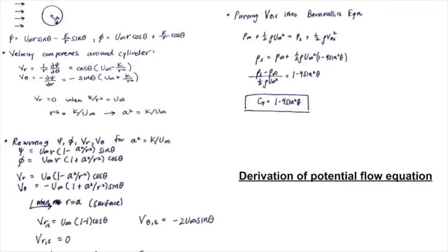Differentiating the stream function with respect to r and theta gives the velocity field of the flow in components of r and theta. Looking at John D. Anderson's text, Fundamentals of Aerodynamics, 5th edition, we see that the interior of the cylinder could be treated as a solid, since the stream function running through the stagnation points given by little r equal to big R and theta equal to 0 and pi are the same. Because we're simulating the cylinder with a doublet and a uniform flow, it doesn't actually know that there's a physical object like a cylinder in the flow, but we can treat it as if the interior were solid.